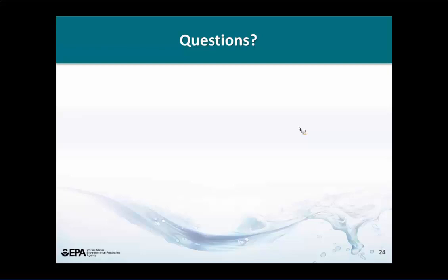Great. Okay, so here's a geek question for you: could you talk a little bit about SWMM, its model time step, and how that model time step fits into curve number calculations and infiltration? Whoever asked that is a true geek. This is covered very well in the first reference manual. You start off with an initial time and go up a time step, and it talks about time steps and Courant numbers and how you keep SWMM from becoming unstable.